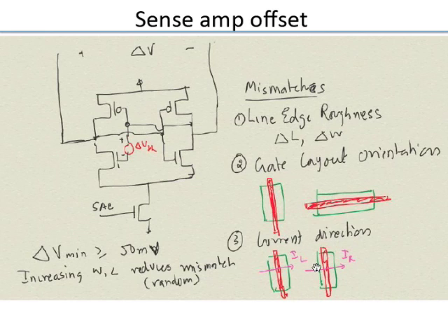The transistors are not symmetric: even though in the schematic we show source and drain and think the behavior is the same both ways, in reality they will have a slight difference. Remember, these are all very small differences. In typical digital logic, you will not notice any of these issues. But when you are talking of these very small voltages, you need to start paying attention to them. So when you lay these out, they all have to be in the same orientation.